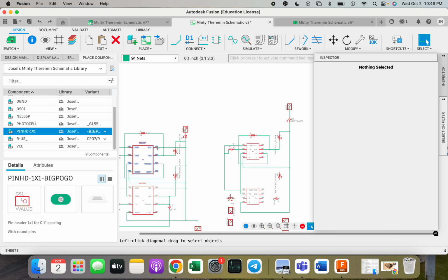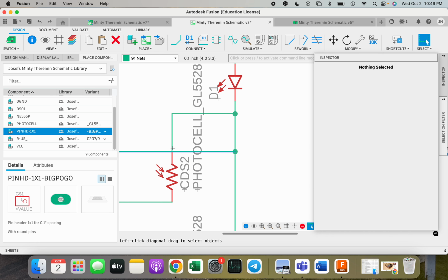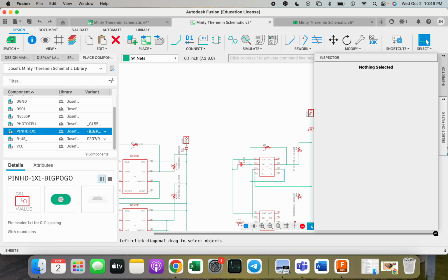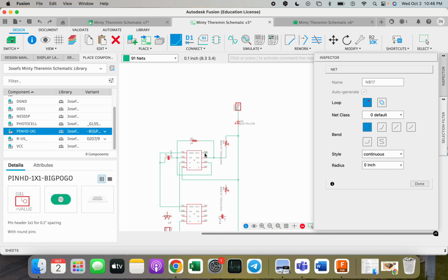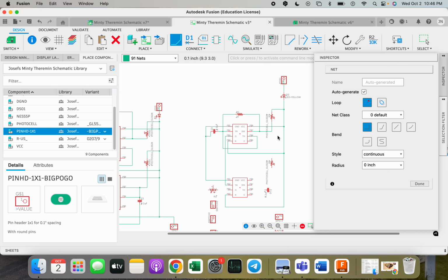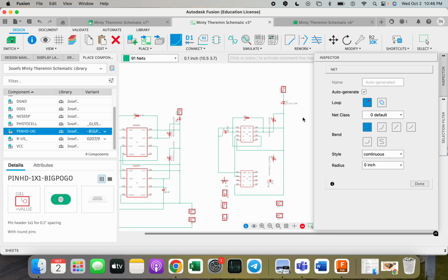So now we can go ahead to pin 8, and pin 8 just goes directly across to the positive line. You'll notice on the schematic there's no dot, so it's not connected to this line here. So we're going to take our net, go from pin 8, make sure that you're getting that little circle, drag it over, and get that solid circle confirming the connection. So now we've completed the top 555 timer.